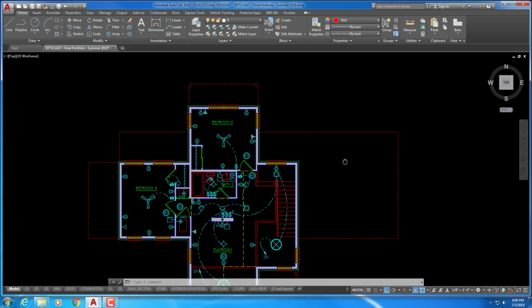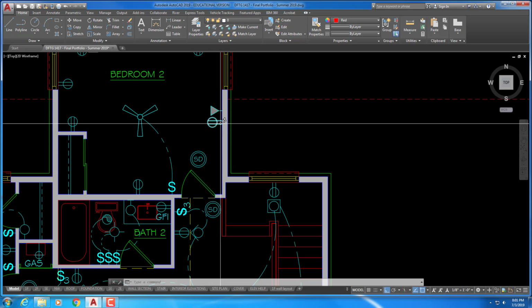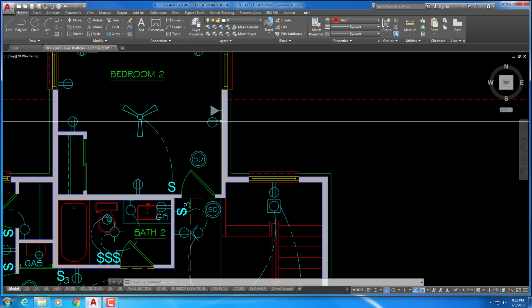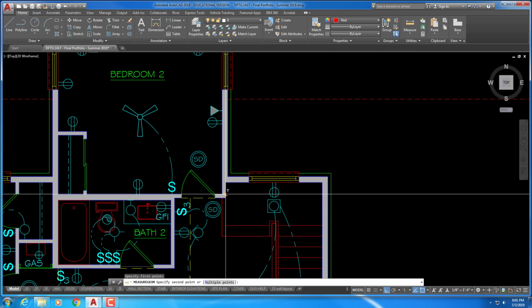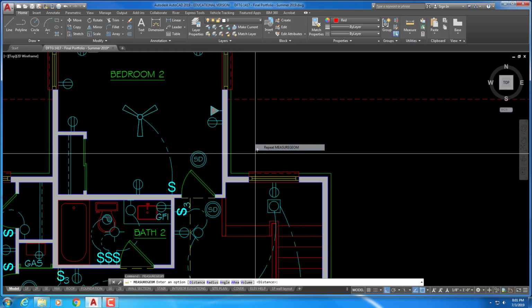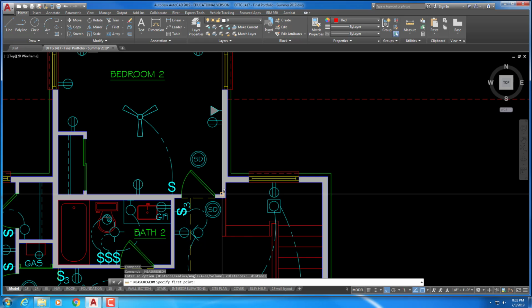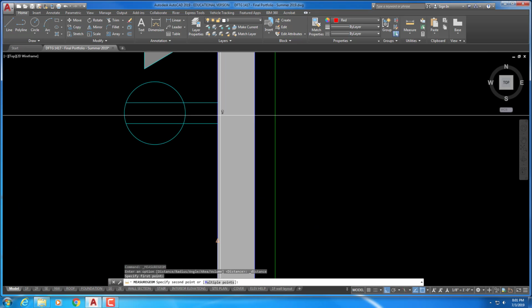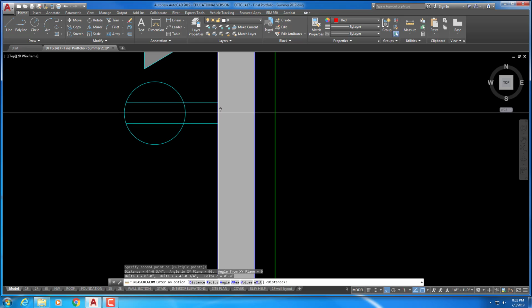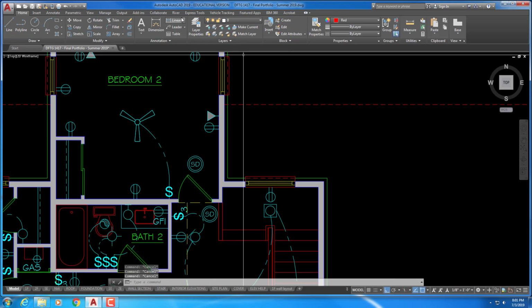I don't think there's anything particularly hard about electrical plans. This is that one case, or at least one case, where if you don't put this in the right place, you might be further than 6 feet. So, you can always check the distance on that. From here to here, it's telling me that's about 7 inches. And in the other direction, kind of to the center there. What is that? 4'0". So it's about 4'8" or so. So that's well within, if I measured that correctly.